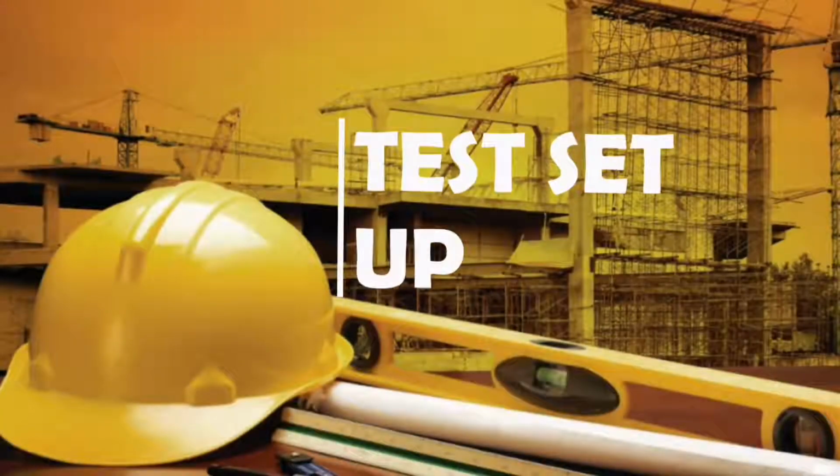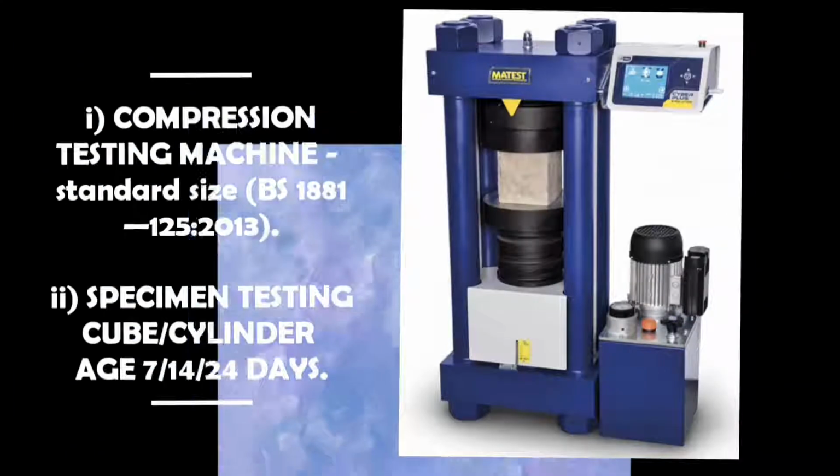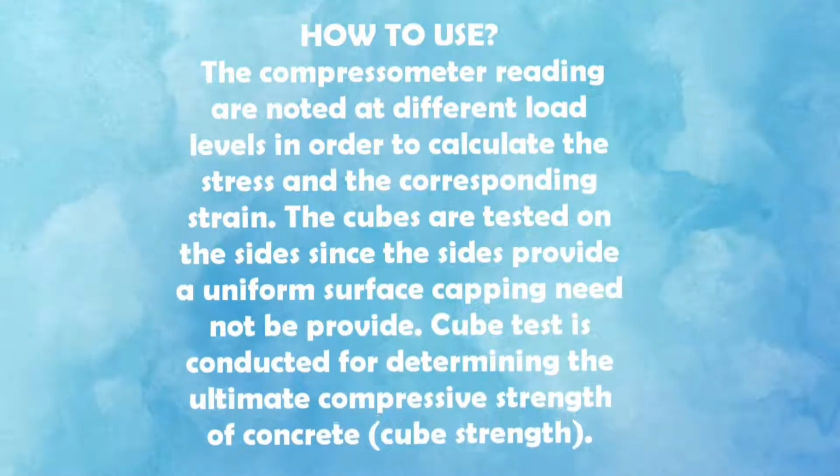Test setup. In this test, a standard test load is applied parallel to the longitudinal axis of a pre-molded and properly cured concrete cube of a standard size. While testing, the compressometer readings are noted at different load levels in order to calculate the stress and the corresponding strain.